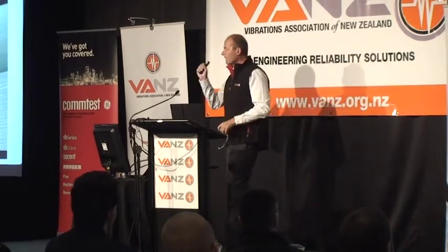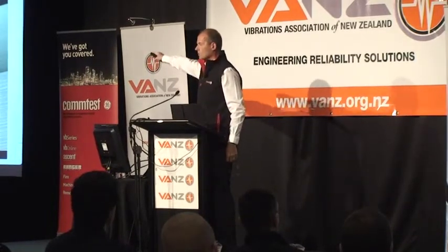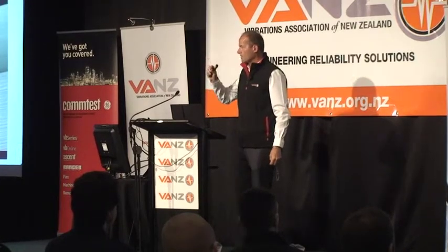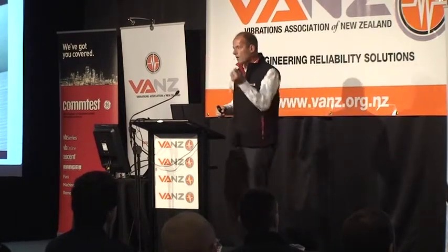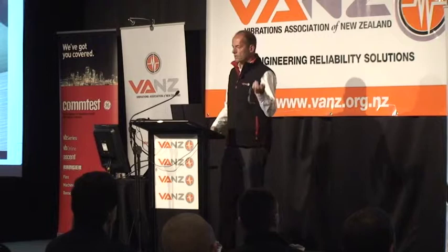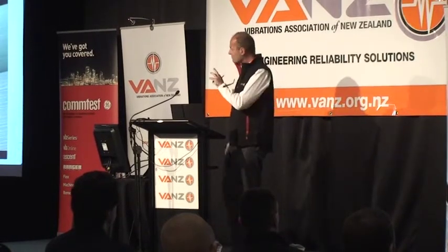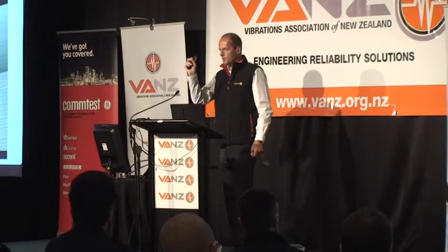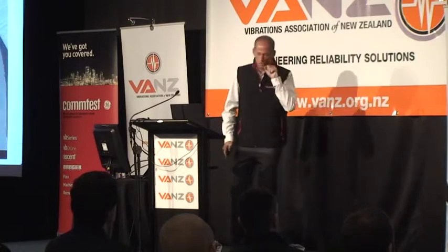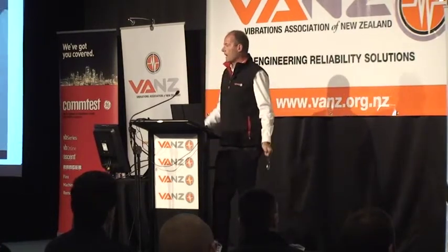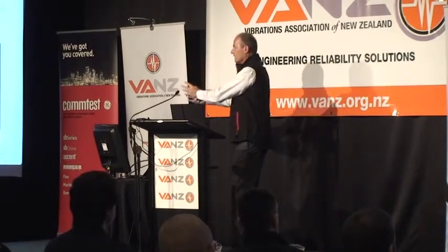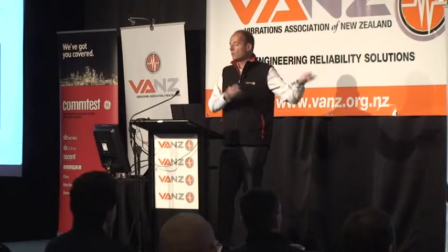And tiny little particles. For my animation I've made it look like a boulder, but we're talking about particles that are just a few microns in size. You can't hope to see those. You can't feel them in the oil. You can't see them in the lubricant or anything else. They are chewing up your machines, whether it's the bearings or the gearboxes. Those particles might cause just a little tiny bit of spot damage, but that damage spreads and harms your machine. And same way with gearboxes, those same particles get in there and damage the machine. So, we can do oil analysis tests to detect this stuff, and we can also try and prevent it.